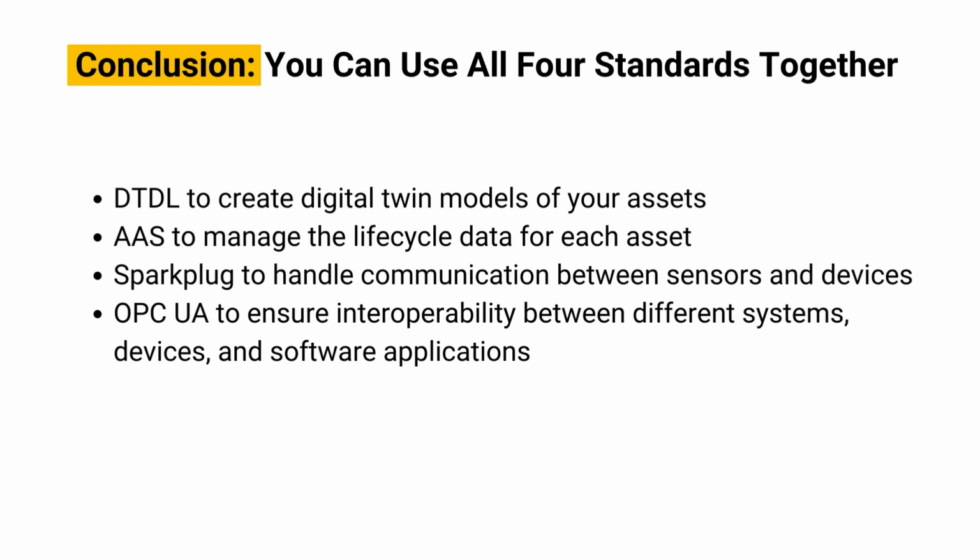In a complex smart manufacturing setup, it is conceivable that all 4 standards could be used together. For instance, you might use Digital Twin Definition Language to create digital twin models of your assets, Asset Administration Shell to manage the lifecycle data for each asset, Sparkplug to handle communication between sensors and devices, and OPC UA to ensure interoperability between different systems, devices, and software applications.